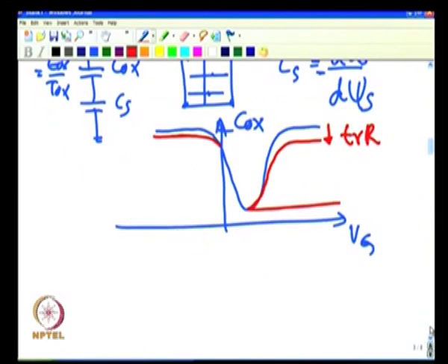And that is why, when we do the oxide thickness extraction using the CV characteristic, we call this oxide thickness an electrical oxide thickness, not a physical oxide thickness. Your electrical oxide thickness extracted from the CV curve may not be exactly equal to your physical oxide thickness, and this could be one of the reasons why.